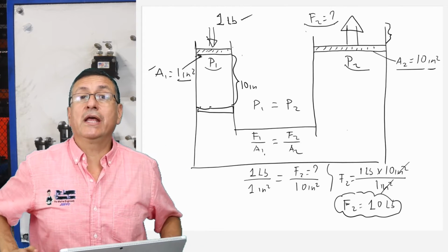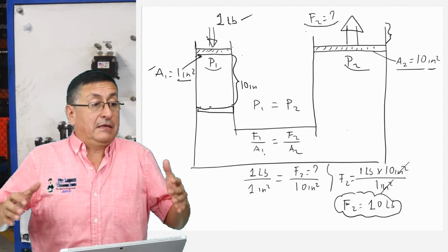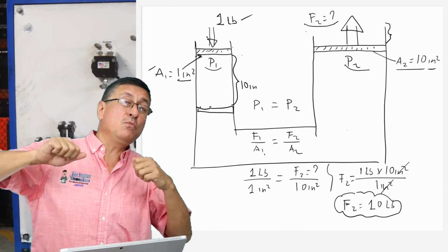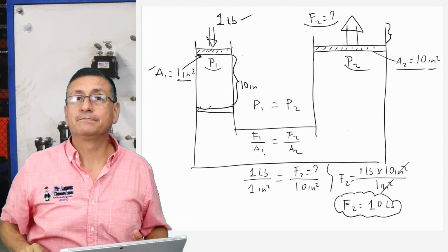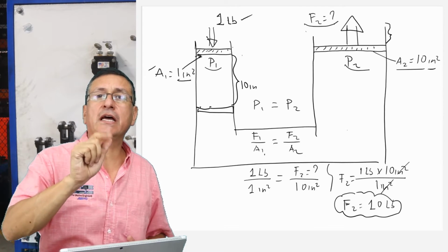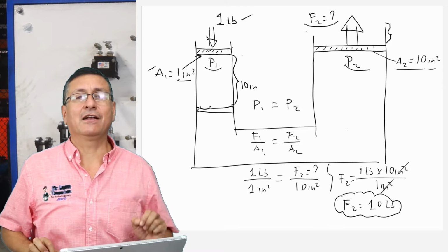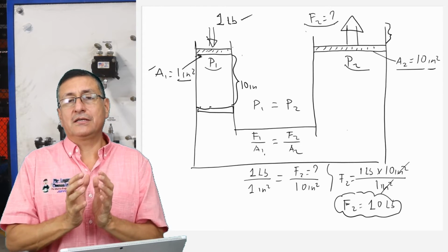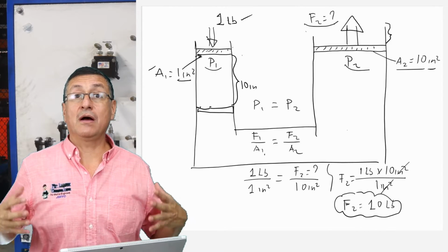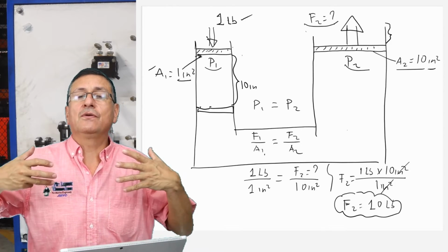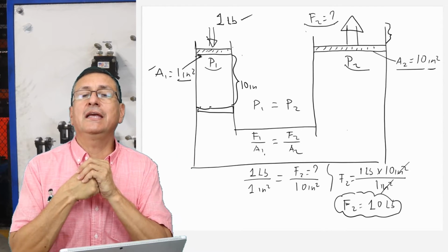Right now, we calculated the output force, and we demonstrated that the hydraulic system multiplies the output force a lot, depending on the diameter of the pipes and the pistons. This is critical. In the next episode, we are going to talk about the cylinders, the actuators, and investigate what happens internally in the cylinders.